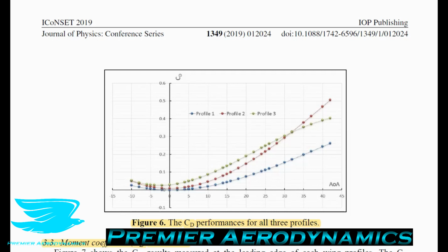The other two airfoil profiles had minimum drag coefficients of 0.007 and 0.0257, and those are normal, like they're in the expected range. For profile 1 to have such a low drag coefficient is a little bit hard to believe. I mean, it shouldn't have much of a pressure drag, but still the friction drag should be fairly high, considering that it should be the equivalent of a flat plate, almost.